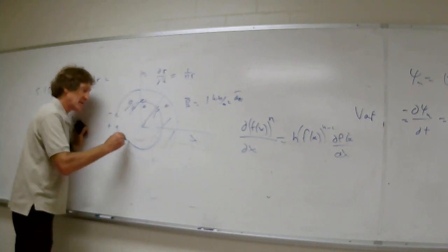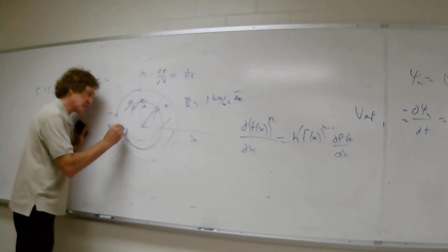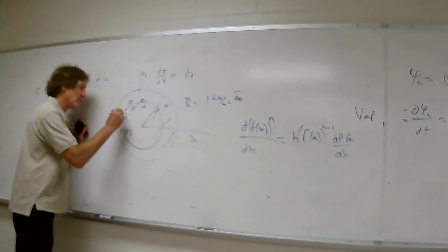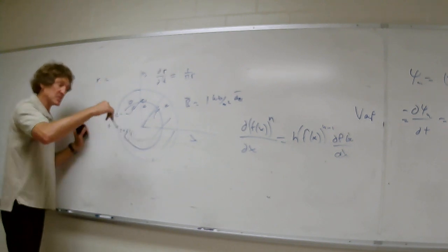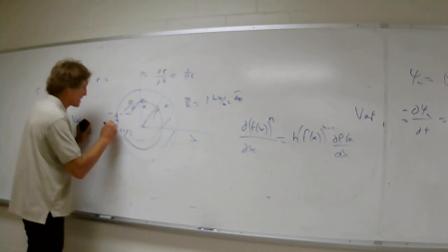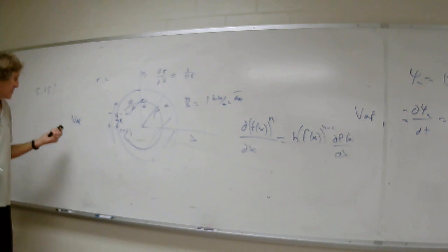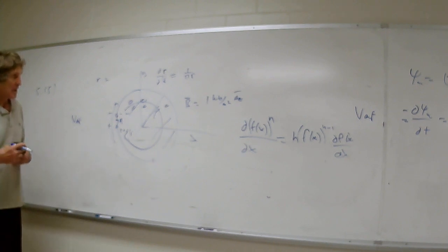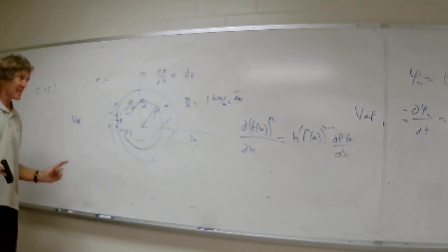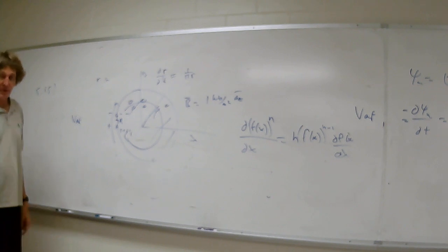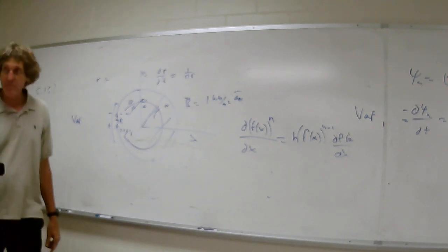The electric field is forcing plus charge here, right? And minus charge here, right? It's trying to force things around. So when we actually put the resistor here, current's going to flow that way. And the current's going to be 2 over 2, or 1 amp, but it's going this way. Y'all with me, class? Yes. Is that what he has? Yes, it's 1 amp clockwise. Yep. All right. Y'all following the method?